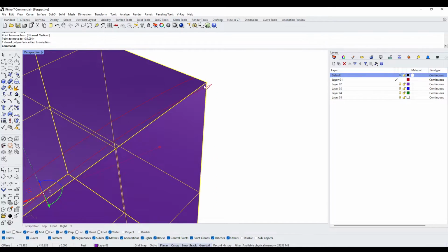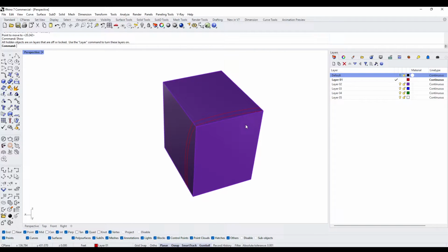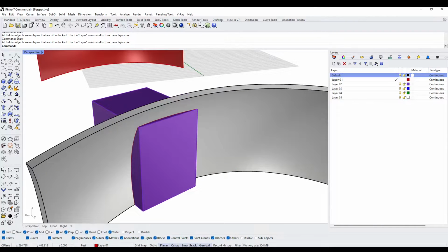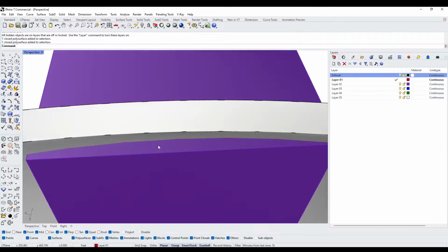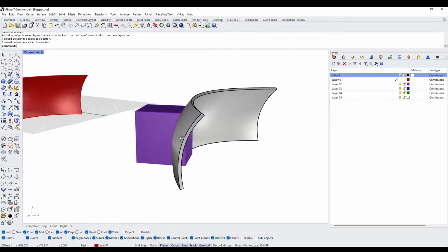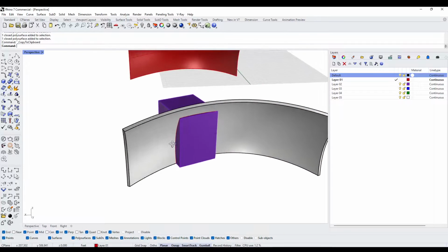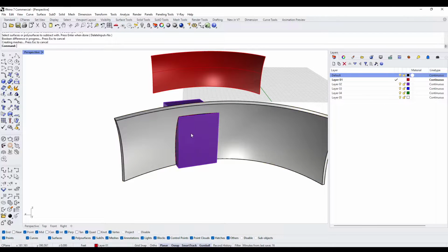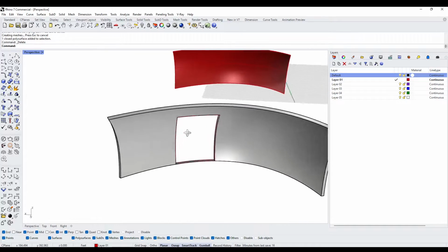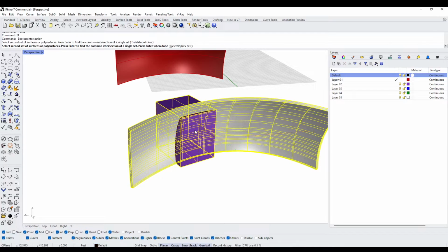The only thing is that we still have that corner not meeting, so we'll actually need to move it to this one. Now I'll type in show, or bring back our wall. And now that we have it intersecting and looking good, now we can subtract it. So we'll copy the wall, Control C, put it onto our clipboard. Then we'll take this Boolean difference, this one, then paste, then Boolean intersection with this one.